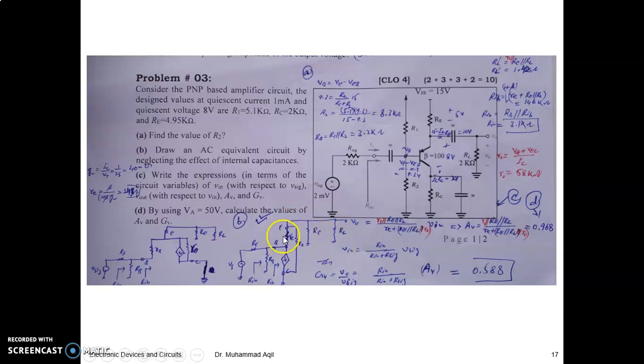And for the early effect, you put from emitter to collector the internal resistance R0. So from the emitter you can see three resistances grounded: R0, RE, and RL. All these three resistances come in parallel, right? So now what we have to do? We have drawn this, now find RE, find GM, right? Find R naught, then this part, the AC equivalent circuit, will be done, right?